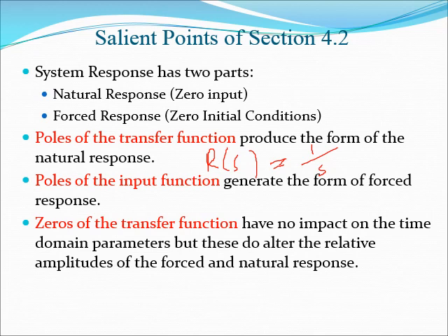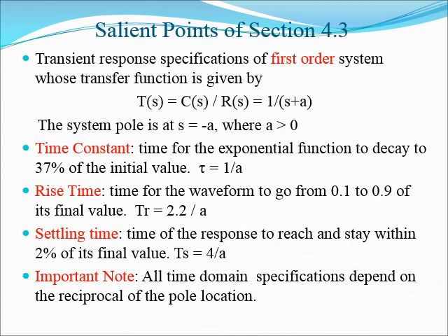Zeros of the transfer function have no effect on the time domain parameters, but they do alter the relative amplitude of the forced and natural response. So what are the effects of zeros on the system response? That is the natural response and the forced response.